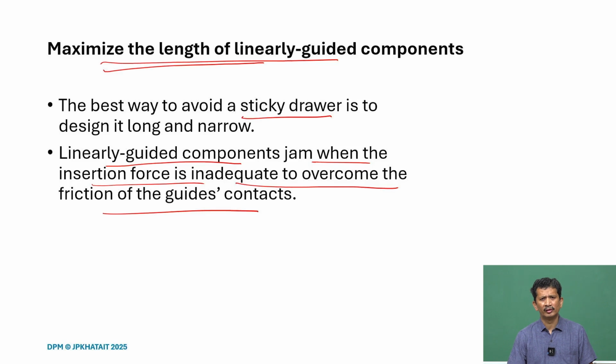That is why whenever we try to assemble, suppose, bearings, it is very important to use proper tools. Otherwise, it is very difficult to take out the bearings or even assemble them, or they can easily damage the surfaces.